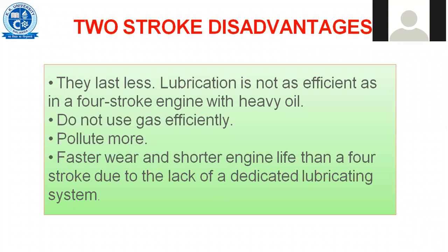But petrol engines will have a lower temperature, whereas diesel engines will have a higher temperature because the fuel has to get ignited by the temperature of this compressed air itself. That means the compression ratio is also very high in the case of diesel engines. That's the reason why normally we don't have diesel engines of two-stroke nature. Any diesel engine mostly will be a four-stroke engine only.